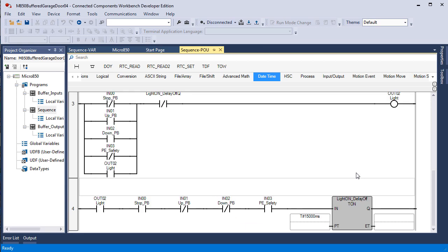If I wanted to narrow the logic, meaning make it fit better on the screen. Once you've been in this business for a while, you'll find that you have rungs of logic that tend to be difficult to read and analyze because they're too wide for the screen, and they do something called wraparound. They actually form a serpentine pattern so you can see all of them on the screen, but it does make it hard to analyze the logic, especially in cases where you have branch arounds, and the branch arounds wrap around, including the main rung.